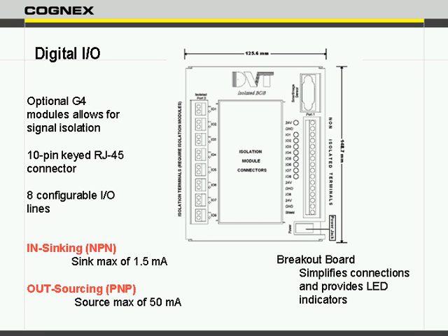But what you would need is either a breakout board, or of course there are people out there that will just cut off the DIN connector on the end of the cable and wire it directly into a breakout board. But this is what we'll be using in this class time to access the 8 configurable I/O points, meaning we can configure them either as input or output.